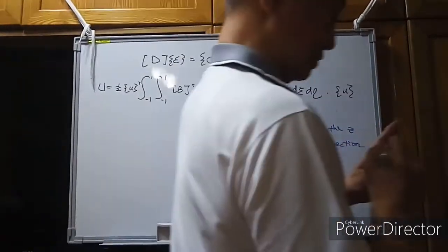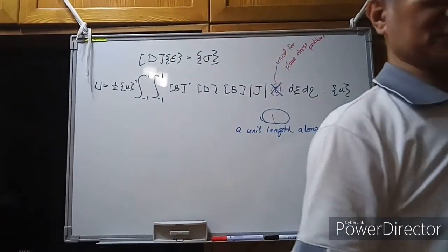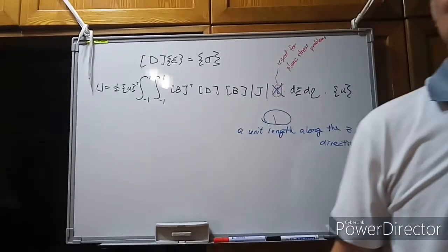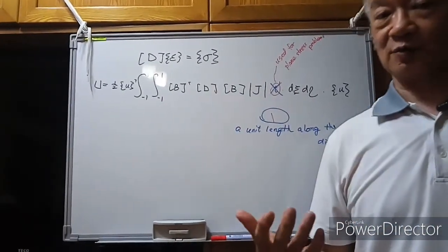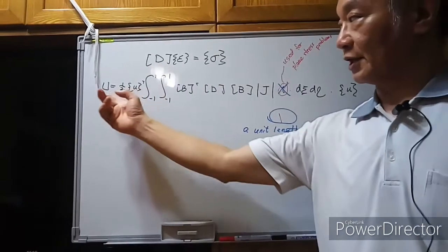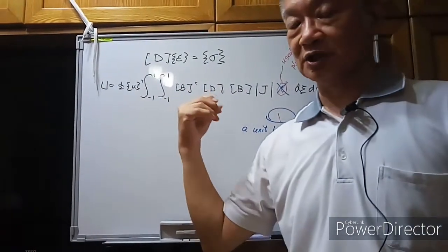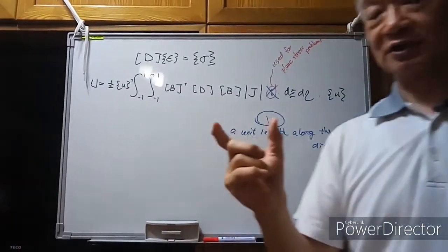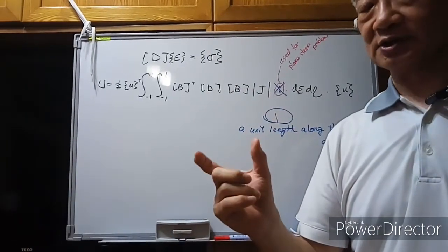Okay, that's another difference between the plane strain problems and the plane stress problems. When we calculate the strain energy, you need to consider a unit length along the z direction.